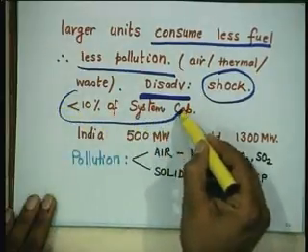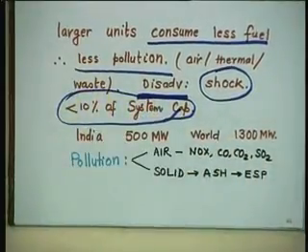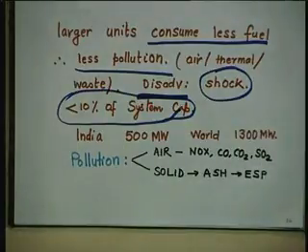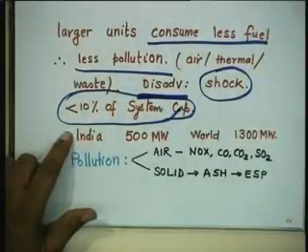Here, where is the question of 1 minute? For hours there is no power. And you can well imagine how much loss, national loss, how much contribution towards GDP, gross domestic product, is withdrawn. But the golden rule is it should be less than 10% of system capability, system capacity. If the system is of 2000 megawatt, we can afford to lose 1 unit of 200 megawatt. That is the meaning of this rule. You can't afford to lose 500 megawatt out of 2000.